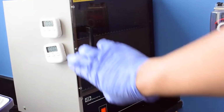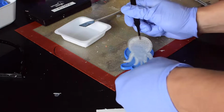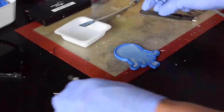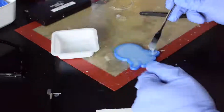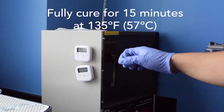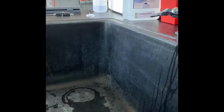We're then going to speed cure this for about 3 minutes at 135 degrees Fahrenheit. And then we're going to take the separator, and using 2 tweezers, we're going to place it in the center of our mold. You can use one of those tweezers to anchor it in place. Finally, we're going to pour the remaining silicone mixture over the top to form the sealing layer. This last step requires a full cure. It takes about 15 minutes at 135 degrees Fahrenheit.